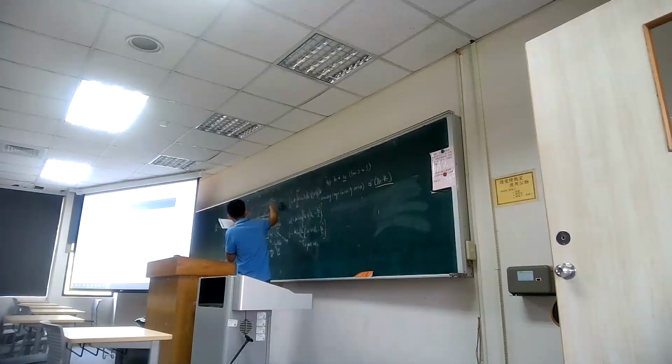That means you get the scaling of this distance over the channel length, the width over the channel length. And the other one is that you can rewrite this as K_n'. In most cases, if you purchase a MOSFET transistor, or you are doing homework or a midterm, sometimes they will say that K_n' equals 1. Okay, so that means you get a μ_n C_ox.